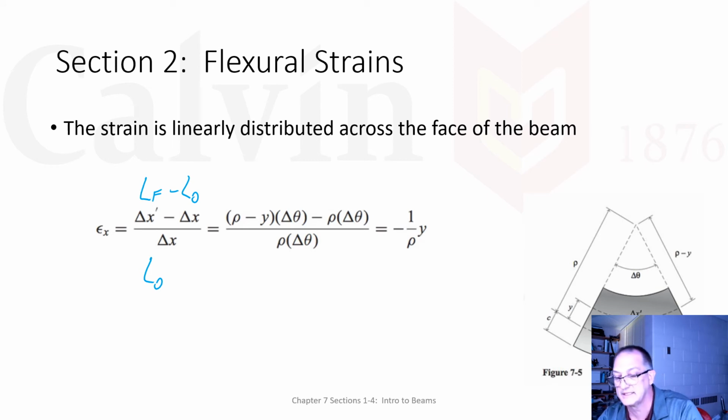So if I want to see this, I'm just going to start drawing because you can't see where I'm pointing. That rho minus y, not p, it's rho. That's the distance rho to my neutral axis, minus that distance y back up. Y is measured positive in that direction. So then I get an actual radius out to that point of rho minus y.